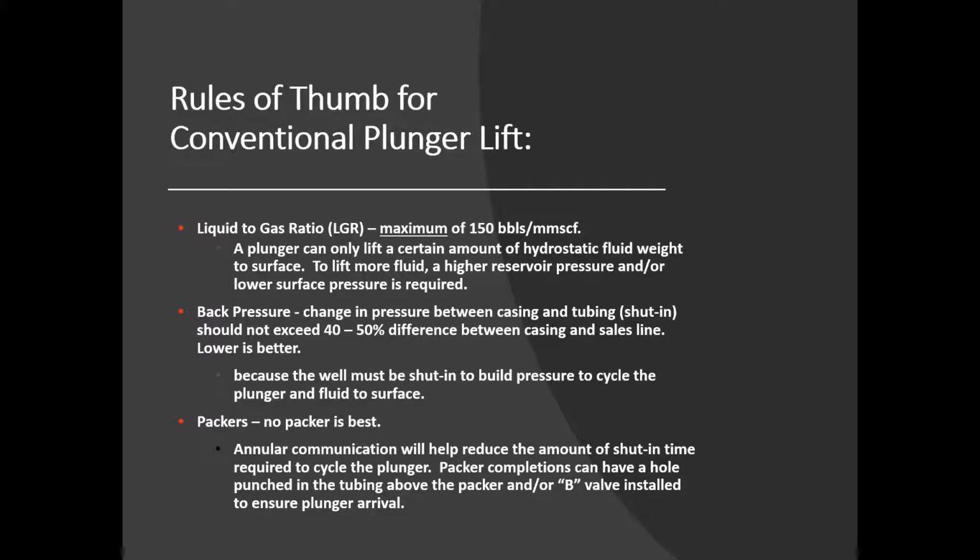Not having a packer is best, but plungers can operate with a packer in the hole. Annular communication will help reduce the amount of shut-in time required to cycle the plunger. Packer completions can have a hole punched into the tubing above the packer and a B valve installed to ensure plunger arrivals. Gas-assisted plunger lift systems typically have packers, however, we're referring to conventional gas drive from the formation with these rules of thumb.